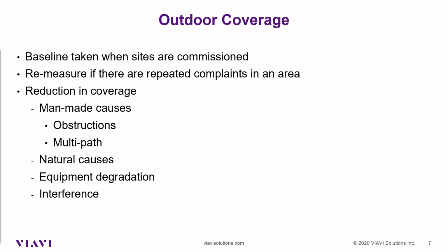You can have an area where coverage is good in most of that area, but in just certain spots, because of the phasing of the signal, you have dead spots, and because of that, it sometimes makes it very difficult to identify what's causing it. And again, you go back in there with a spectrum analyzer, and you go, well, the signal level's fine, but here, having the right equipment, being able to go in there and measure the actual signal quality, we can find sometimes that maybe there's some other things happening because our signal quality is not what it should be, and that's why the receiver is not receiving the signal like it should.